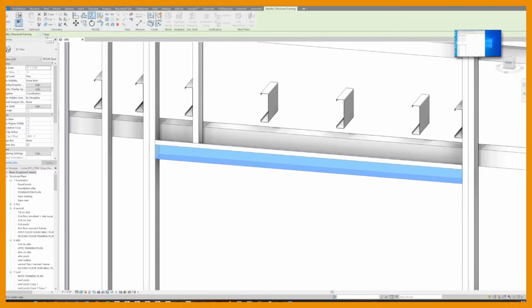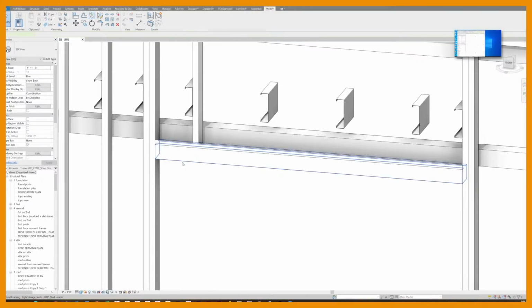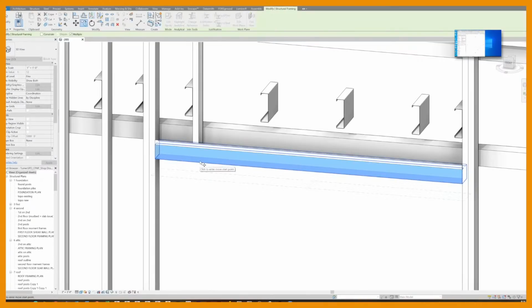Notice it says copy, right? My first tip is really just to pay attention to that bar, realize it exists, and realize the power that it has. But the tip from Paul is, if you are doing something like a mirror, if you press Control on your keyboard and hold it, it'll actually uncheck or check the copy, which is pretty cool. That's for mirror, but if you go to copy an object or move an object, you have a couple of options: constrain, disjoin, and multiple. If I hold Control and let go of it, you'll notice it's flipping between disjoin and constrain. But if I press Shift, it's unchecking or checking constrain. So pretty cool tip. So two tips in there, I guess.